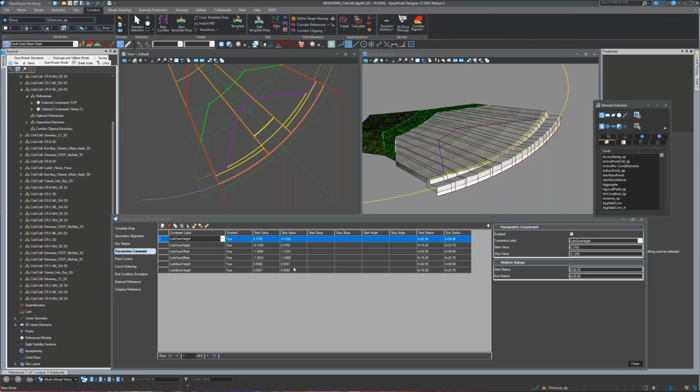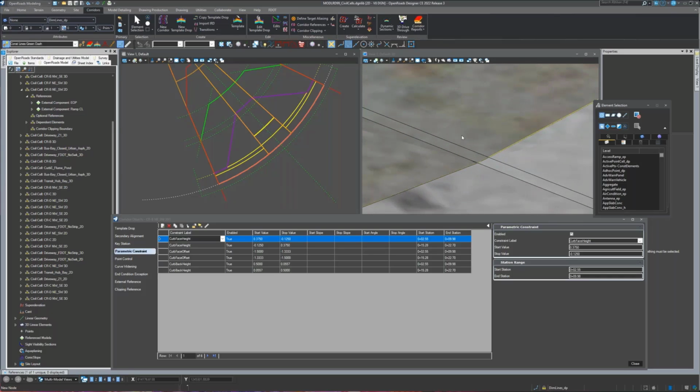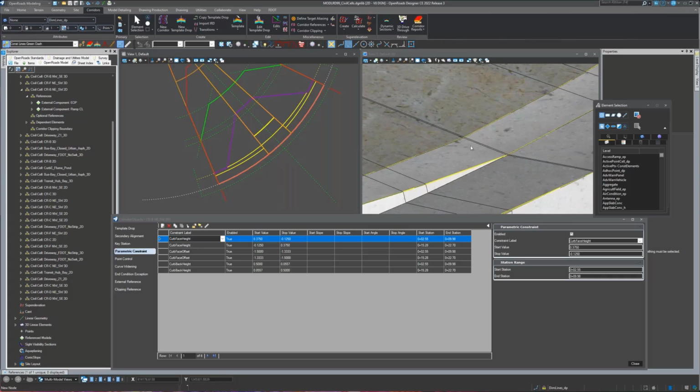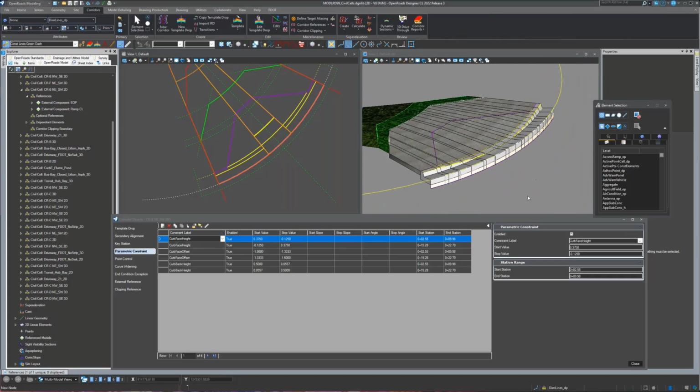And then you could come in here and figure out what the vector offset is and slightly change these 2 parametric constraints to match what your actual slope is. And then you'd have this thing coming down perfectly. It's really close, but it might not be exactly perfect to the decimal point. But if you've got some situation where it's way less or way more than 1/12, you'll definitely see it.